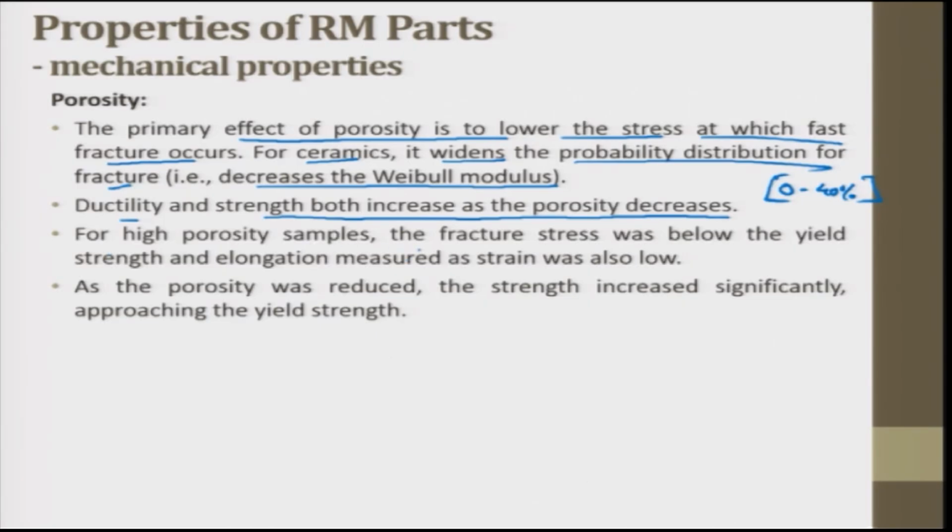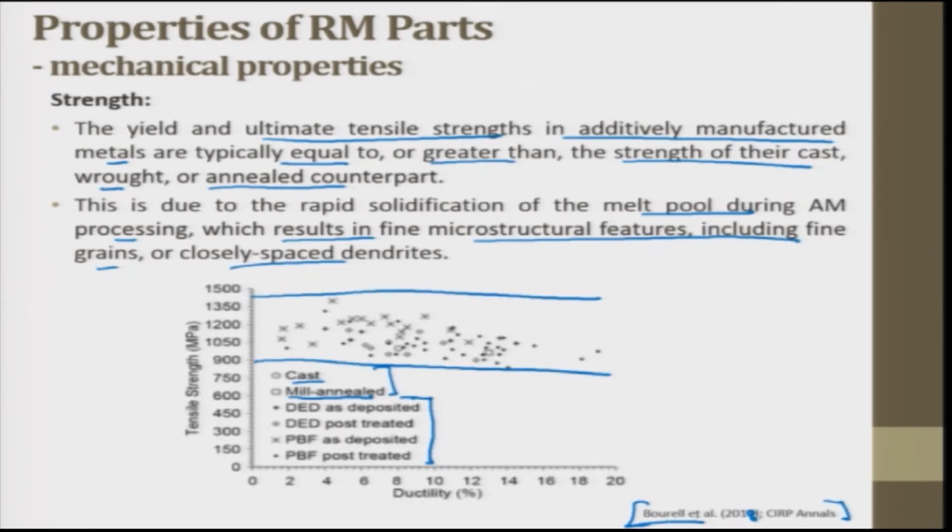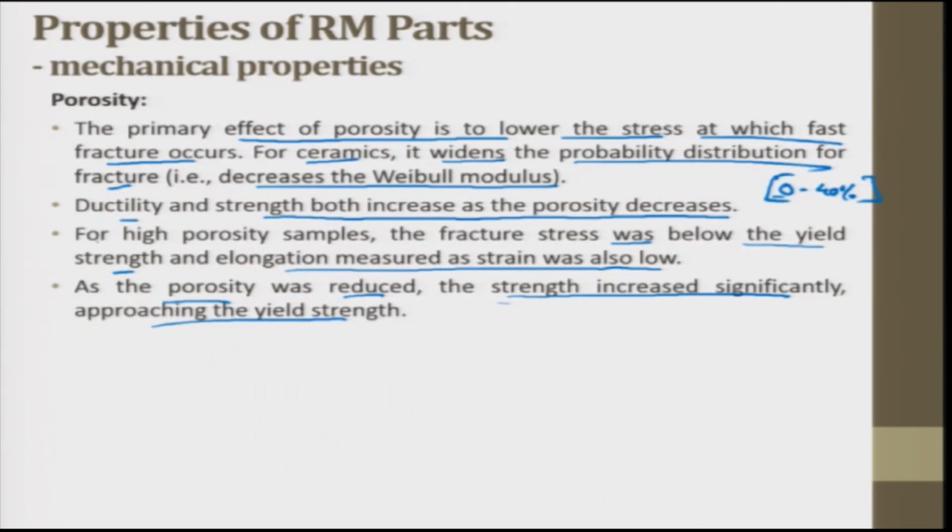For high porosity samples, the fracture stress was found to be below the yield strength and the elongation measured as strain was too low. As the porosity was reduced, the strength increased significantly, approaching the yield strength. This was again a study by Borel et al. They studied laser sintered polyamide samples with varying amounts of engineered porosity. This porosity ranged from 0 to 40%. So this was the inference they came up with.